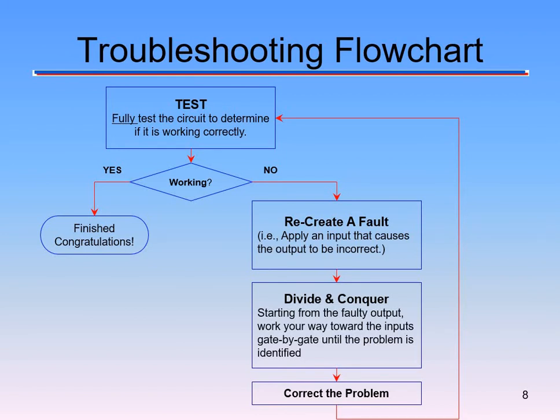All right, some of you guys, we've already run into that with breadboarding. I accidentally wired up the AND gate as an OR gate and vice versa, and that completely conflicted all your problems. And that was one thing where we knew, oh, well, we should have been getting, 101 should give me a 1 here, and it's giving me a 0. So you've got to think about, do I have the right chip in the right location? So think about all these things.